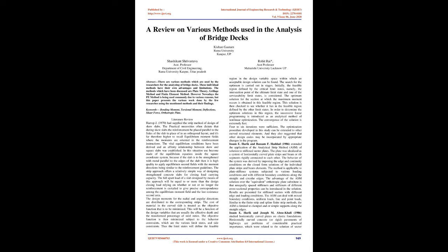Horizontally curved concrete, or rigid, pavements of highways are problems of considerable practical importance, which were related to the solution of sector plates on elastic foundations. The purpose of this research was to present an analytical solution for sector plates that are supported along the edges and resting on an elastic foundation. Effect of the subgrade reaction. Results are presented for sector plates with different edge and loading conditions. Different values for the plate. The solution procedure is an extension of the analytical strip method that was previously developed by Herrick.